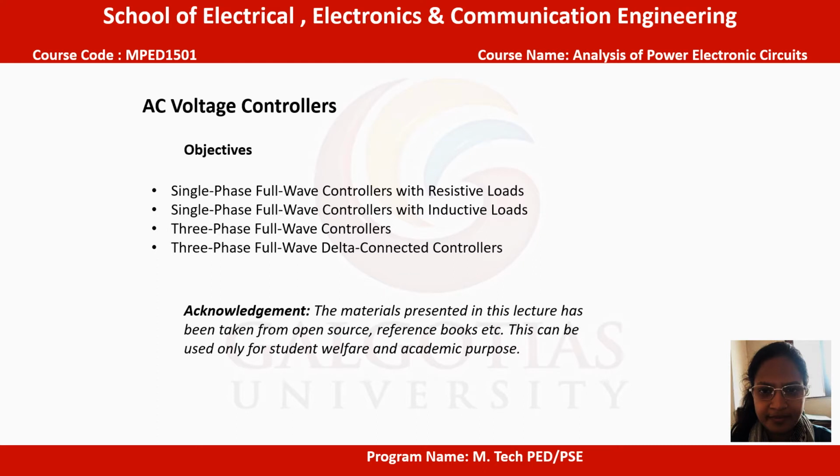There are various configurations of three-phase controllers depending on the connections of thyristor switches. Since the input voltage is AC, thyristors are line commutated, and phase control thyristors, which are relatively inexpensive and slower than fast switching thyristors, are normally used.